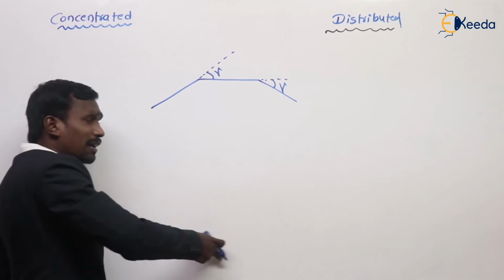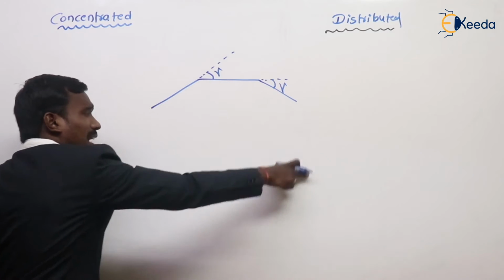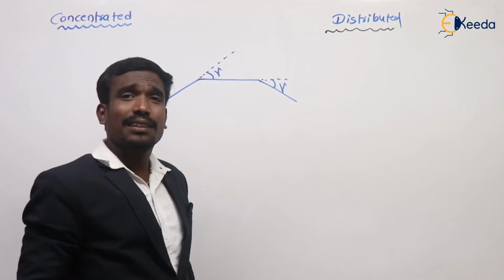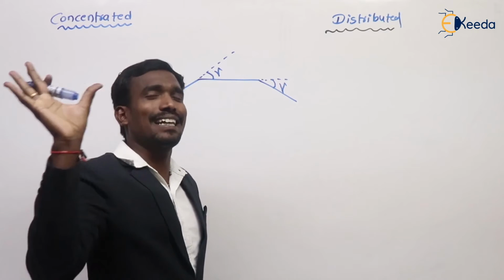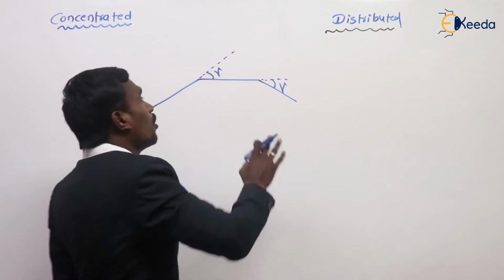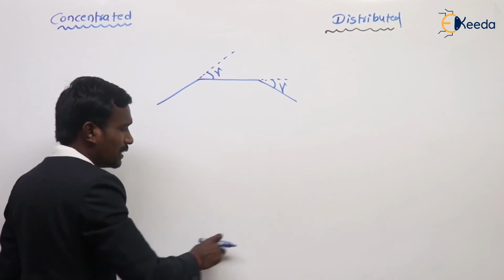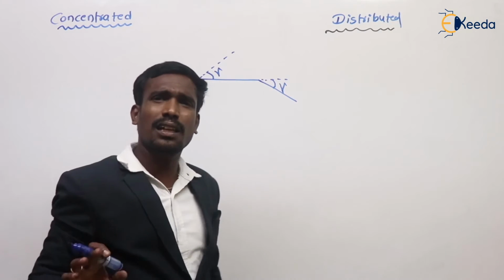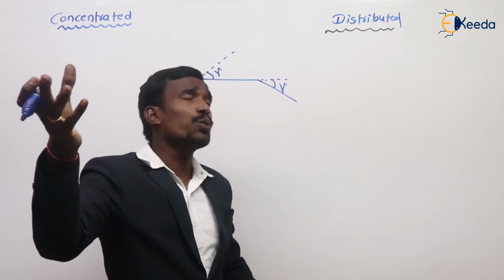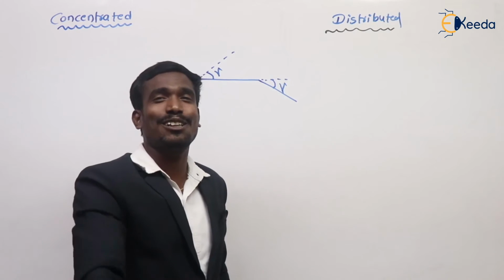If there are more slots, then it comes as a pure circle. If the diagram is a pure circle, then the EMF waveform is pure sinusoidal. Here I have just 3 slots. If I have 30 slots, the next one is a pure circle. If m is large, we can get the circle, then the EMF waveform is a perfectly sinusoidal wave.